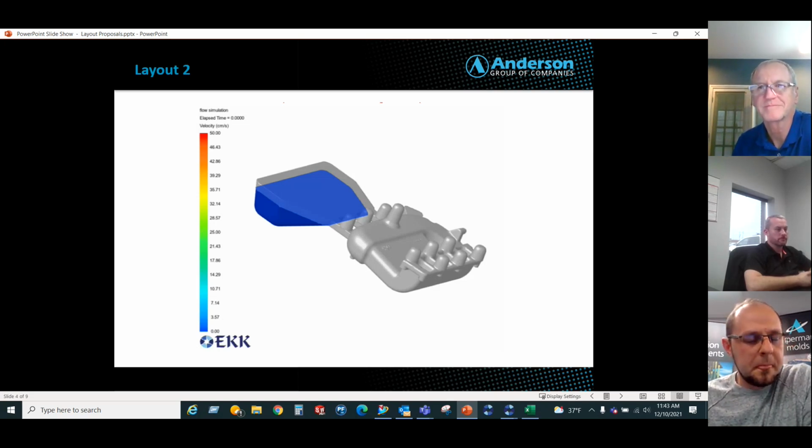Correct. Yep. That we definitely start simple first, and mainly that is for post processing in the foundry, less gates to degate and things like that, and less things to grind. Yep. Degate.